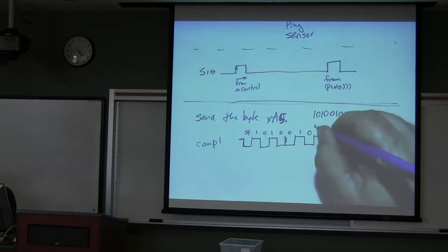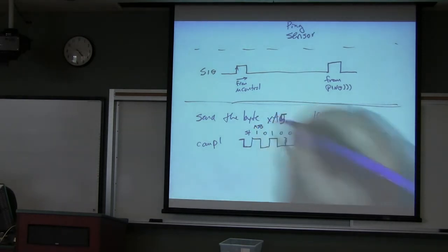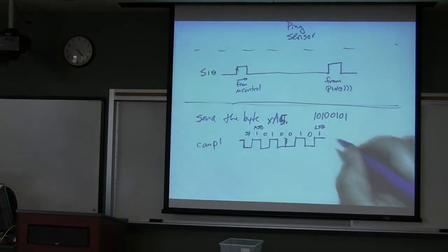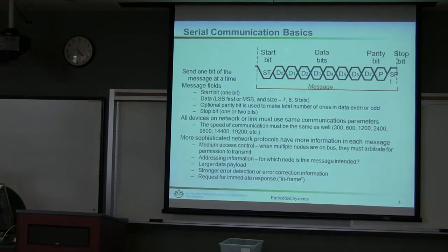By the way, this is the least significant bit. This is the most significant bit. And then I'm going to have a stop bit. What did I say my stop bit was? Oh, I'll do parity. Let's do a parity bit, and I'll call my parity even.